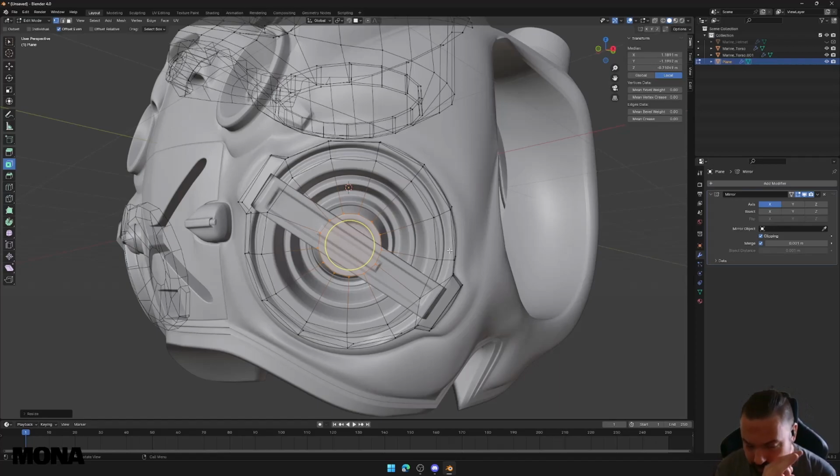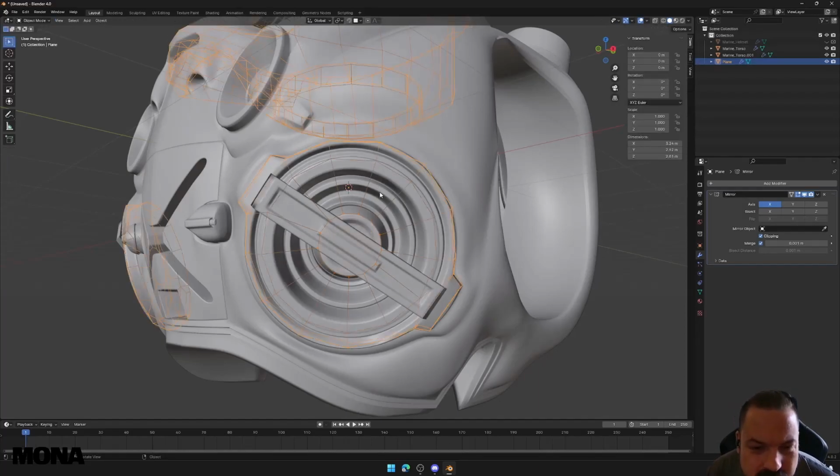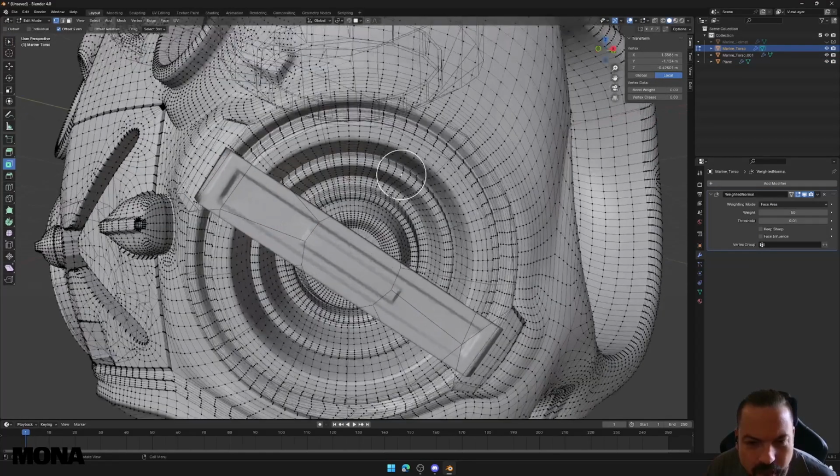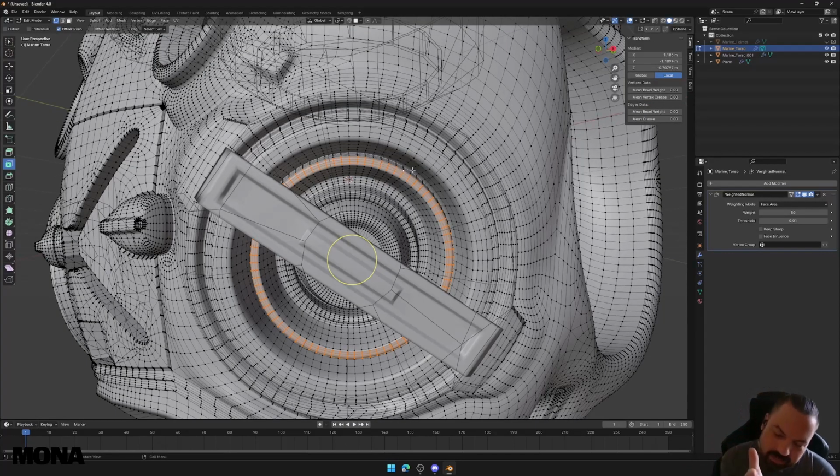What I could possibly do is design the high polygon mesh in a way that the low polygon bake looks better, right? So say, for example, I would go into this, and I would maybe grab all of these and rotate them to the low polygon so it bakes better.